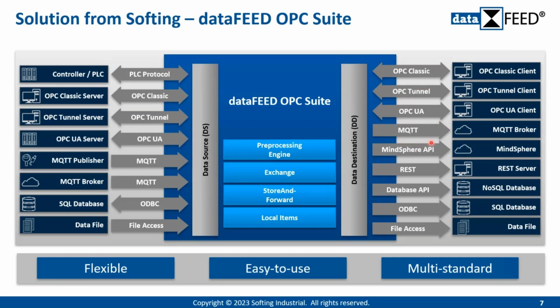We are able to provide the information via MQTT to a broker. We can directly connect our suite to the Siemens MindSphere. We have a REST interface for providing the data to a REST server, a database API for different kinds of NoSQL databases. We have the possibility via an ODBC driver to put the data in a SQL database. Also, last but not least, we are also able to write the data in a file.